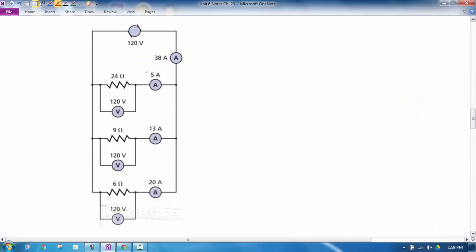Okay, so now if we hook up a parallel circuit now, what's different is the voltage across the battery is exactly the same as the voltage across each resistor. Because you can kind of tell it doesn't matter whether you hook the voltage probe up here or whether you hook it up here. You know, there's no resistor in between necessarily to change anything. So it's going to give you the same voltage reading of 120. And that's the advantage of hooking things up in parallel, is you're not basically losing energy per charge from the other items that are hooked into the circuit. So you're supplying 120 joules per coulomb of energy to each of the items in the circuit, to each of the resistors or each of the appliances or whatever it is you're hooking in.